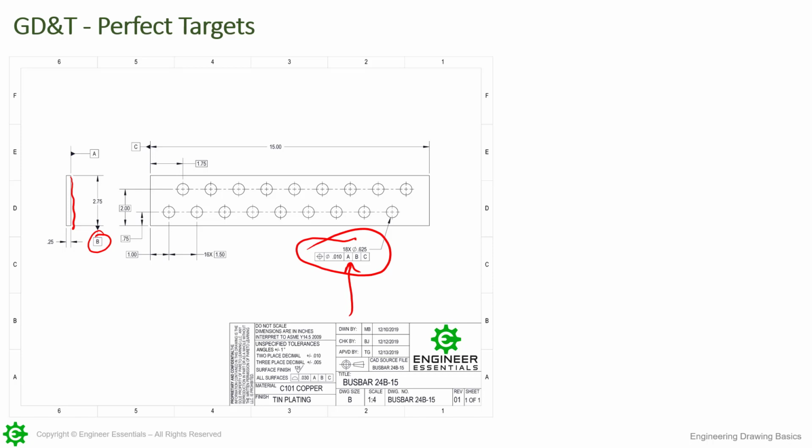Now notice that on B, it's in line with this dimension. With it being in line, that means that we have a midplane here. And then now everything will be positioned or located about that, but we could have taken on this datum here, not put it in line with the dimension and just moved it over here. Get it away from that. Remember, anytime it's in line, it's going to treat it as a feature of size datum or midplane datum, sometimes called a width datum also. But we could put it over here to the side. That would mimic what we had in that first drawing where it's here and here.